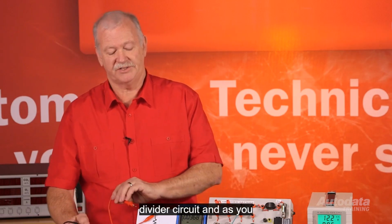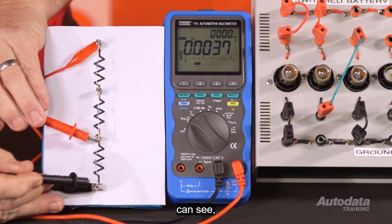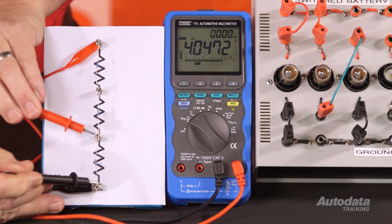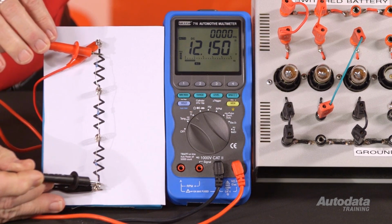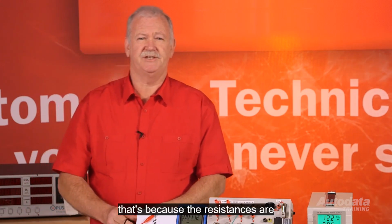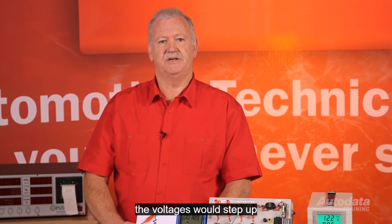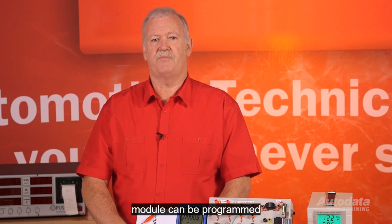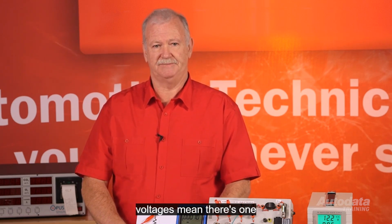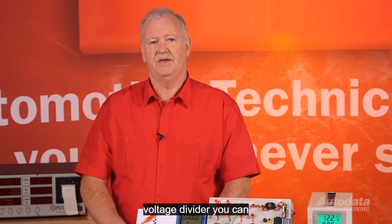Here we have a voltage divider circuit. And as you can see, the voltage increases evenly. That's because the resistances are even. If the resistances weren't even, the voltages would step up unevenly. Either way, the module can be programmed to understand what these voltages mean. There's one drawback to this type of voltage divider. It can only send one piece of information at a time.